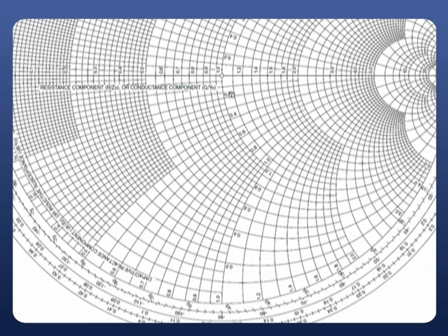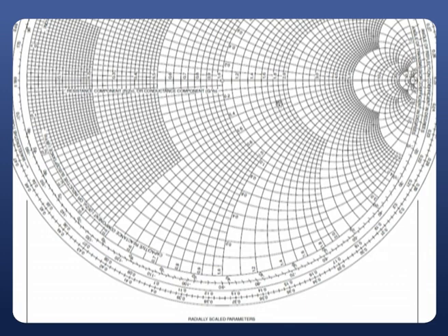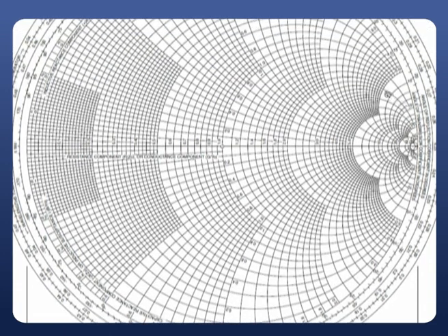Now observe different properties of our Smith chart again. Once again, I will just recap. The complete circles always represent the resistance circles, and the partial circles always give us the reactance circles. In those reactance circles, positive reactances are above the horizontal line, and negative reactances are below the horizontal line. This is our point of open circuit, this is our point of short circuit, and this particular line is said to be the maximum voltage line, and this particular line is said to be the minimum voltage line.